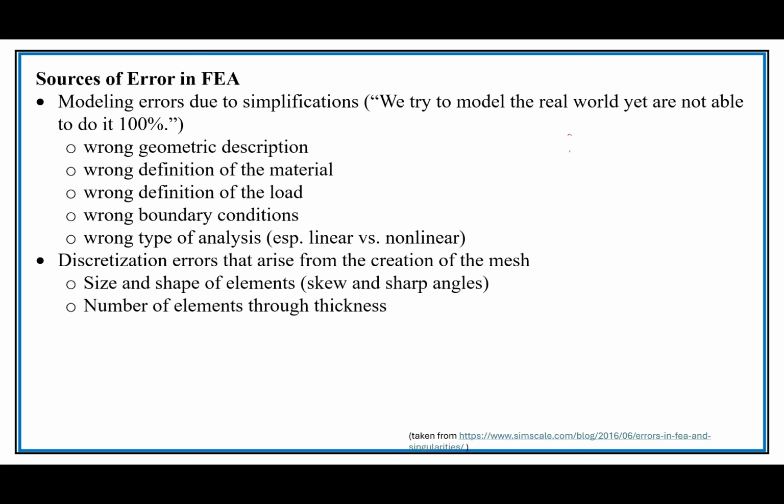Of course, obviously the number of elements through the thickness is really important. If you have a very thin thing and you've made only a couple elements through there, it's not really going to capture the physics. You're really almost going to need to make a much tighter amount of elements passing through there, so that you will capture the true stiffness of the piece.